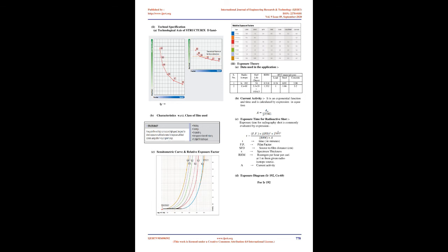Quality control. Production, placing, compaction. Standard batching procedures can be used for naturally occurring aggregates such as barytes and magnetite to allow for the increase in aggregates' relative density. It is sometimes necessary to use smaller drum mixers, approximately 0.5 cubic meters and smaller, for lead shot. Normal batching and handling equipment can be used, but great care should be taken not to overload the equipment as HDC is much denser. Batching times will take longer per cubic meter, but individual batch mixing times should be similar to those for standard aggregates.